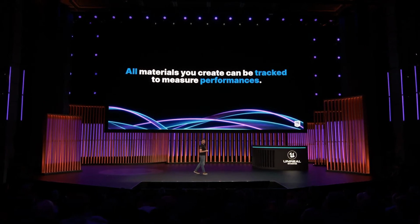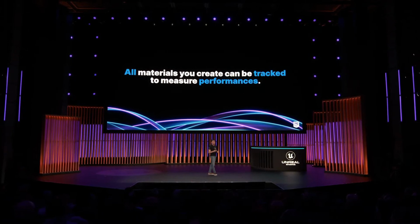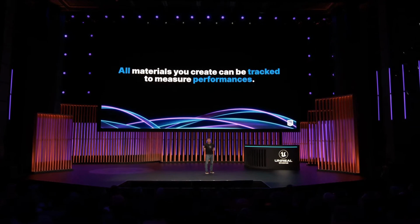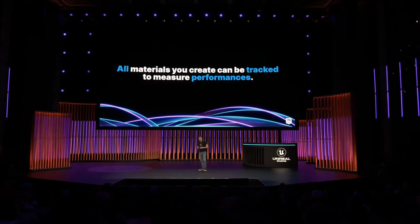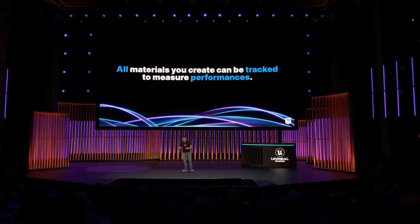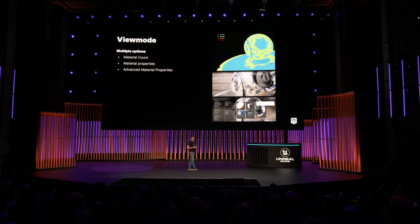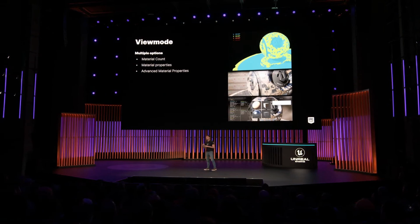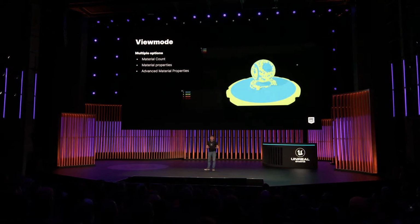All right, with all those effects, you will need to control the performance impact of your creativity. To help artists and engineers to have some feedback, Substrate is coming with different tools to dig inside this layering system. Various view modes have been added to track your material complexity. As you know, stacking multiple BSDFs could be expensive if you're not too careful. However, Substrate will help you to find the best combination between performance and quality.